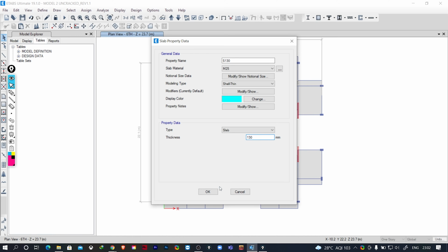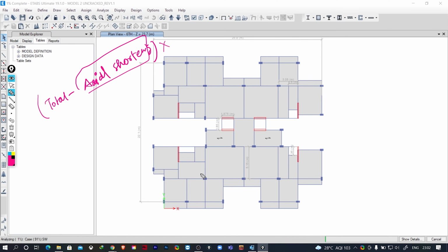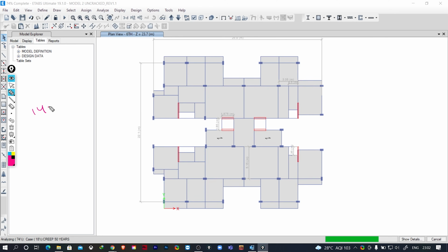Because the value that we are getting was total deflection, including the axial shortening, right? So we need to check the axial shortening also. The process is total deflection minus axial shortening. We do not have to multiply the creep coefficient here, because this axial shortening is added; we are seeing the total deflection of the structure. So what is the deflection or shortening of the column? We need to check. This thing we have skipped. That's why maybe 32 values are coming. The limiting value is something around 14.7. You can say 15.